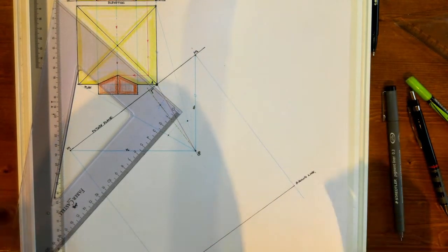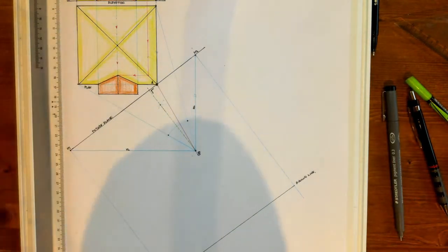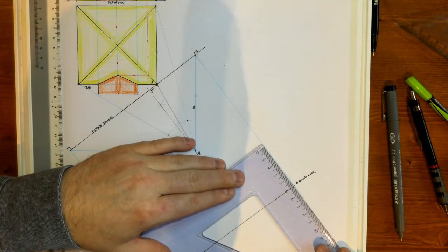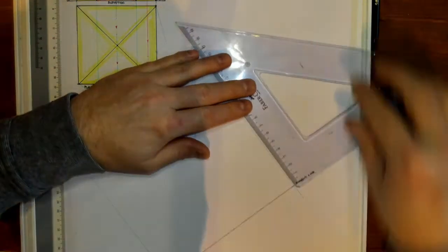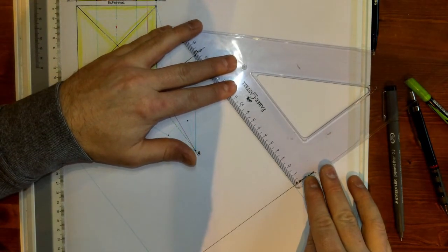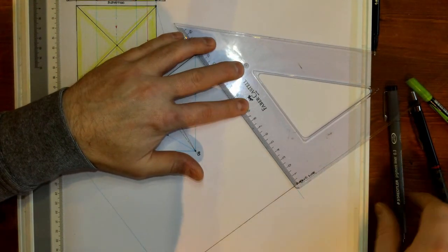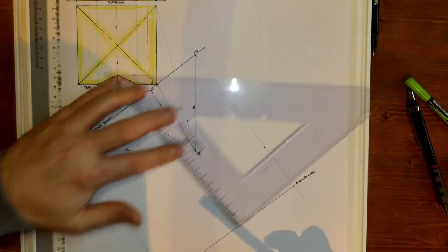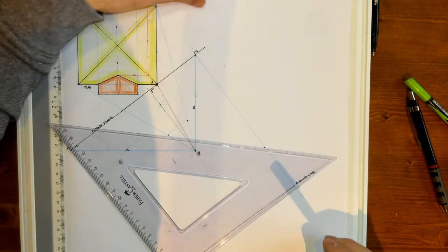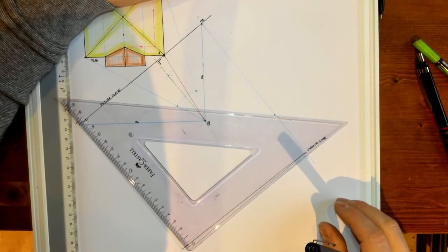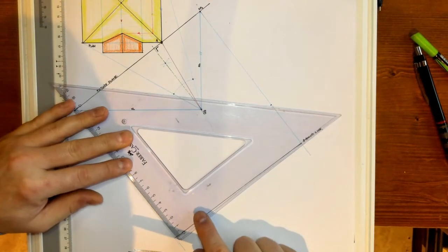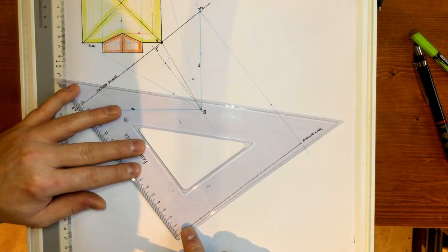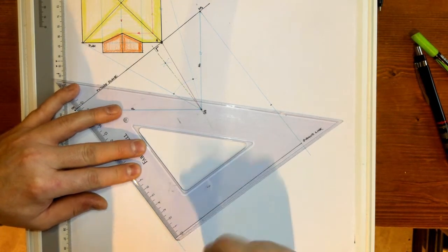Now, so I have the ground line here, that's like our XY line. Now I'm going to apply the measurement for the horizon line, which was 50 millimeters. So, 50 mil above the ground line here, on the vanishing line that I have, I am going to mark my 50, like so. And I'm going to do the same down on the bottom side. So that you can see here, 50 again, from the ground line up on that vanishing line, and we mark it like so.